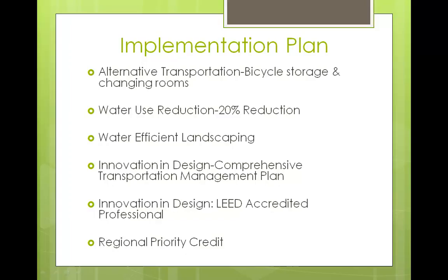In the Water Efficiency section, Water Use Reduction by 20%, prerequisite 1, with changing a few types of fixtures, this prerequisite can be met. For example, if the water closets, urinals, shower heads, and sinks were changed out, then the water usage will be reduced by approximately 47%.